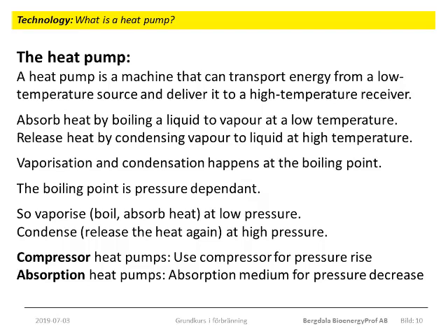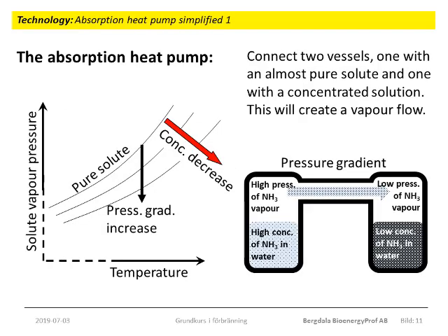So what we want to do is to use the district heating produced from the outlet steam to produce district cooling. To do that, the smartest way is to use an absorption heat pump. And let's now look at the theory and how this works. It is well known that the vapor pressure of the solvent is reduced when the concentration of the solute in a binary mixture increases.